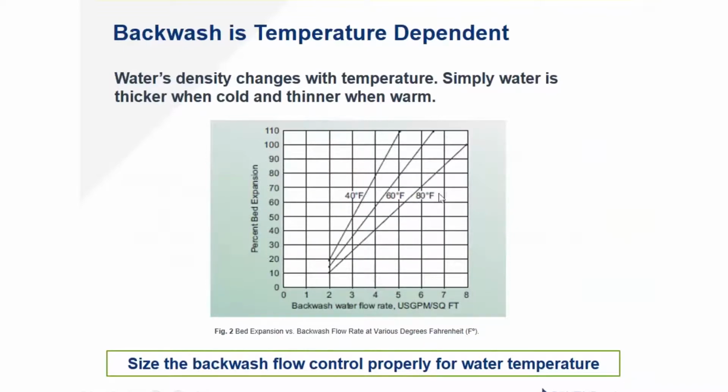In some parts of Texas, the tap water ends up coming out of the tap above 80 degrees during the summer just because of the ambient temperatures. I even know people in Texas that will shut off their water heaters in the summer just because you don't really need it. So understand regional effects based on water temperature are going to impact your backwash.